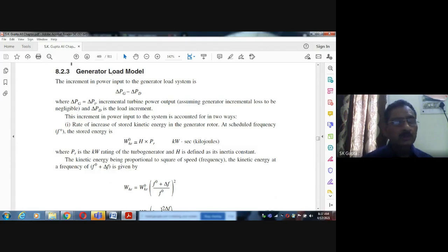So what happens is, if the demand is high before the control, I am talking before the control, as we described in the earlier lectures, it takes the energy from the rotor, so rotor speed goes down. When the rotor speed goes down, the frequency goes down.